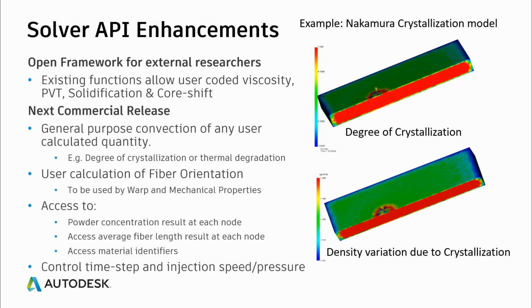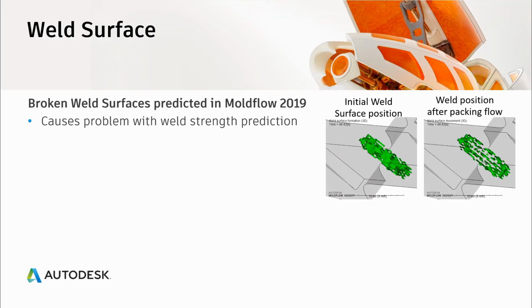And lastly, we've done an enhancement to allow the control of the time step size during the flow analysis and to allow the control of the injection speed and packing pressure control during a flow analysis. And this we had done to allow integrations with models of molding machine behavior, which were being developed by an injection molding machine manufacturer.